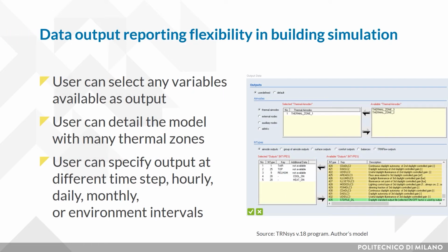Dynamic building simulation represents a powerful tool to support designers in high energy efficient building design. Nowadays, simulation tools are characterized by a high level of detail and high reporting flexibility. Simulation runs usually generate a big amount of data, for the following three reasons. The modeler can select any variables available as output, and normally the programs are able to calculate hundreds of them. The modeler can detail the geometrical building model with many thermal zones, thus increasing the output numbers. Moreover, the user can specify output at different time steps like monthly, daily, or hourly.